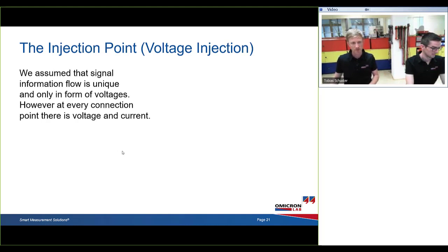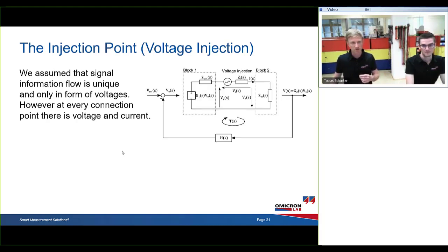Of course that's very simple, and there is a lot of detail behind that, why that works. You can calculate a lot of math about that. You can make an equivalent circuit for the injection point. So you can say when looking backwards there will be a signal source that generates the voltage that is visible at that point, and after the injection resistor, so looking forward, there will be someone that picks up the signal that has an input impedance, and then you can work out the voltages and the currents at the injection point